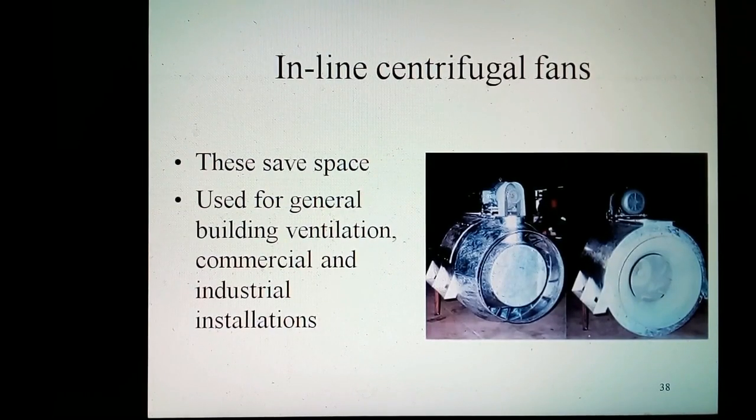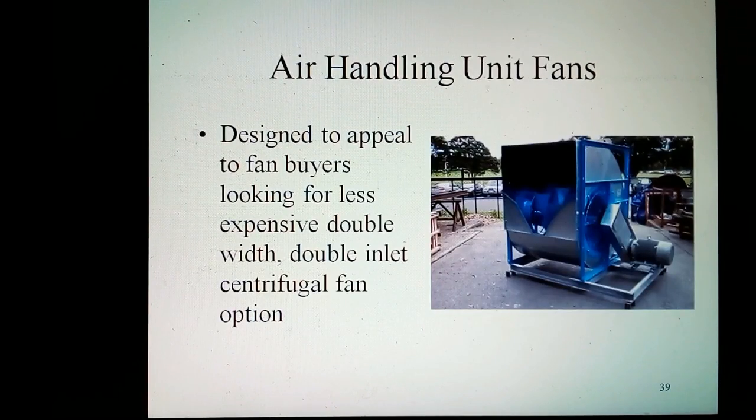Inline centrifugal fans combine the performance characteristics of the traditional scroll-type centrifugal fans with the space-saving advantages of axial-type fans. These fans are applicable for general building ventilation, commercial and industrial installations. Air handling unit fans, designed to appeal to fan buyers looking for a less expensive double-width, double-inlet centrifugal fan option.